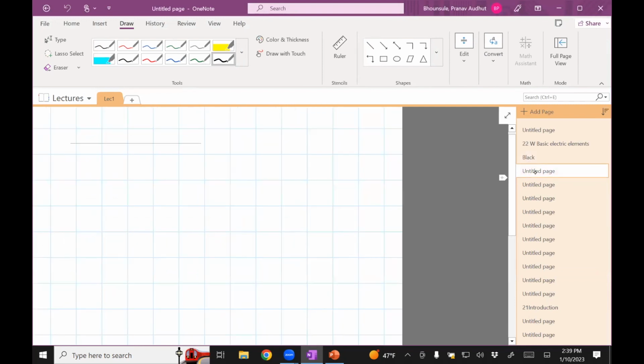Now, there are other resistors which I think are very interesting. Potentiometer is one of them. A potentiometer is a variable resistor. What that means is that you can set its resistance. It's basically a system with a knob, and if you turn the knob, it changes the resistance of the potentiometer. So if you don't know what resistance you need to use in a circuit, you put in a potentiometer, and then you can switch the resistance.